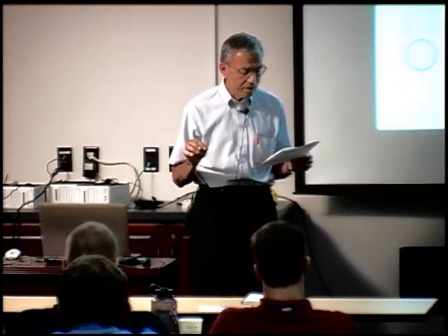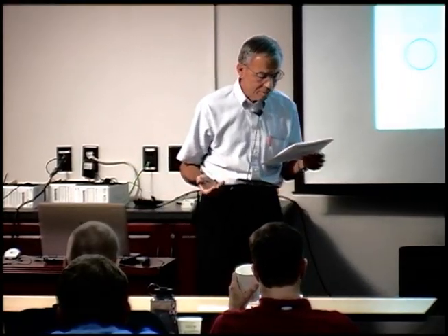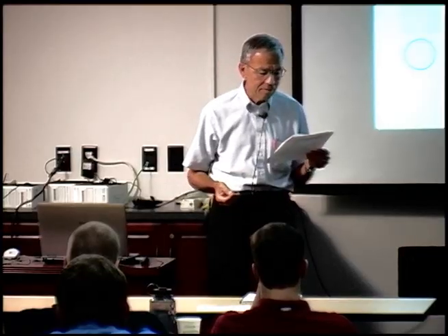One of the things that became apparent is that under our old allowable stress system for driving using WEAP analysis, there was quite some variation in how soon bearing was reached. The minimum I've got down here is about 55% of the pile length.